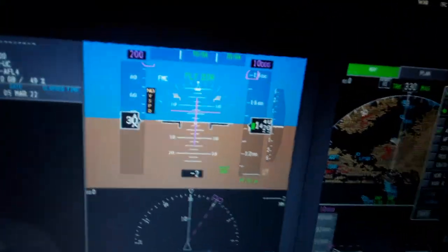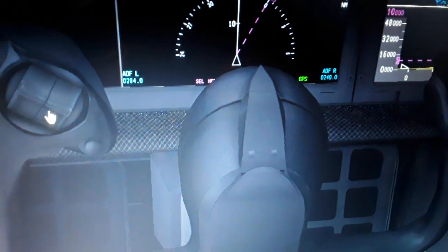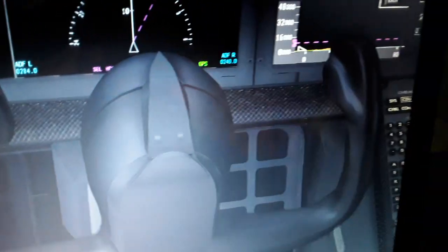So you have also the manual pitch trim over here. So you trim the elevator up and down like this and use all flight controls. So this is a fly-by-wire aircraft. It has its flight control computers control the aircraft attitude in flight. Like the Airbus aircraft, we have the normal, the alternate, and direct modes of flight control computers. Also we have the automatic trim function of the aircraft.